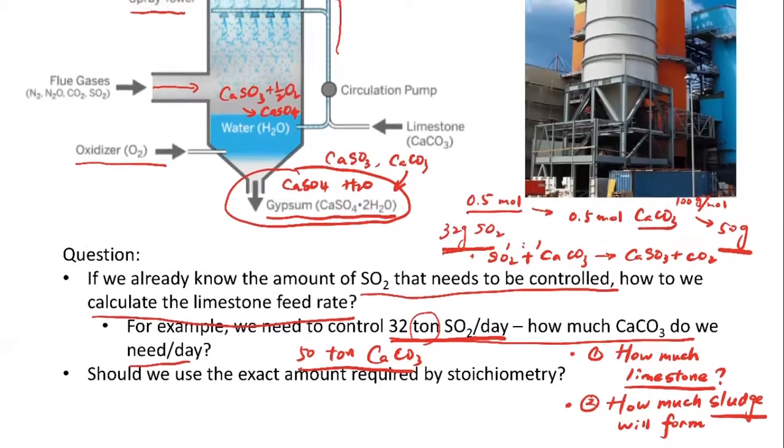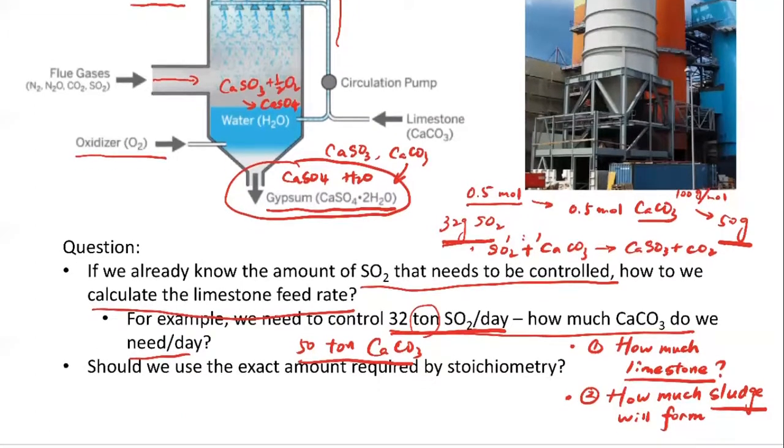For now, if we assume that the limestone is purely composed of calcium carbonate, then based on this relationship, we can calculate how much of the calcium sulfate we're going to form from this process, right? We know that everything is reacting at a stoichiometric ratio of 1:1. So what that means is we're going to form 0.5 moles of the calcium sulfate, right?